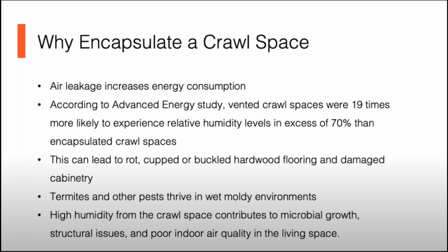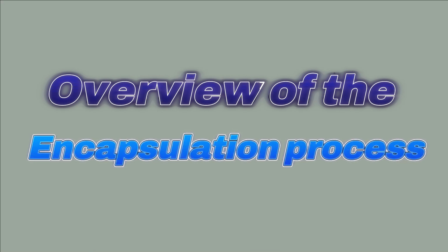These high humidity conditions allow termites and other insects to thrive while also providing conditions conducive to microbial growth. Other issues with these high humidity conditions include the potential for structural issues and poor air quality in the living spaces. As you're seeing, there are a lot of reasons to not have vented crawlspaces. As we've become more advanced in the construction and pest control industries, we've figured out that encapsulated crawlspaces are a great solution.